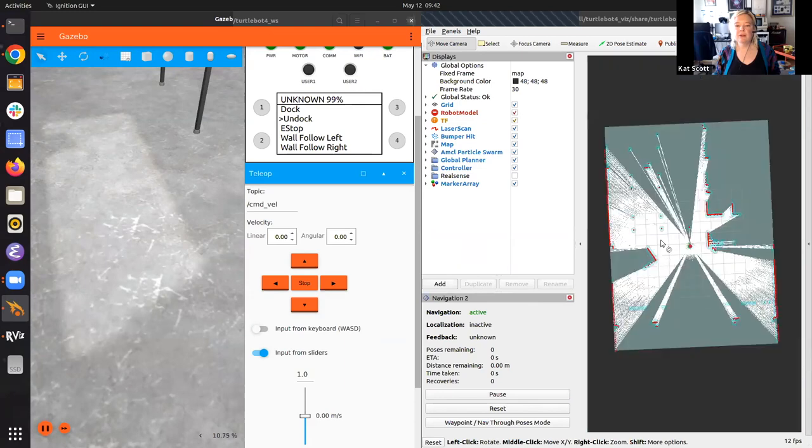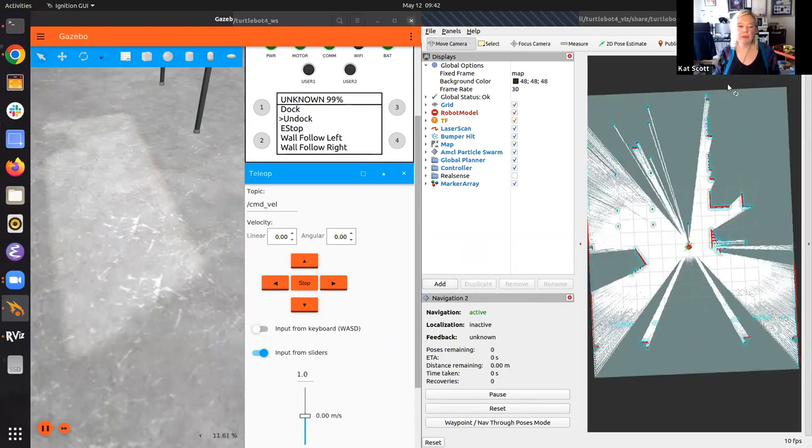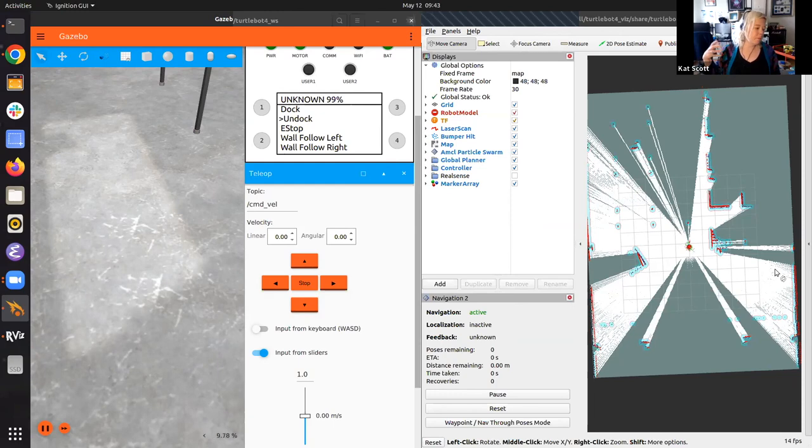And then what you see here is a 2D top-down view of that whole room with a simulated LiDAR. We're showing where all the edges are, where you're going to build your map. I'm not going to sit here and do it all, but you could drive this whole robot around, build a map of it, and then navigate from point A to point B, or do some predefined behavior. And you can do this all with the simulation.